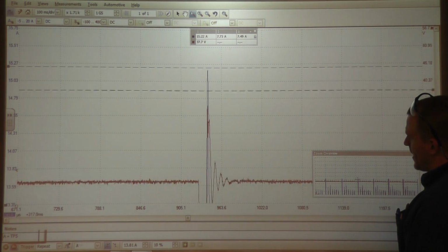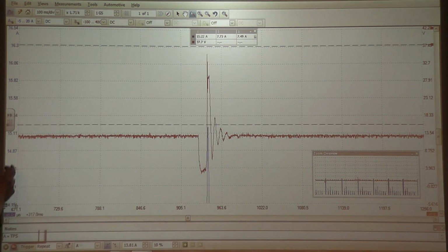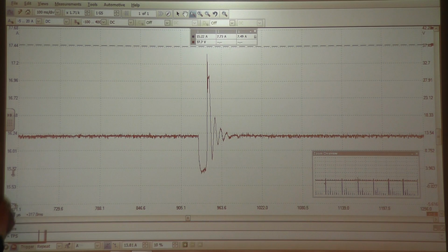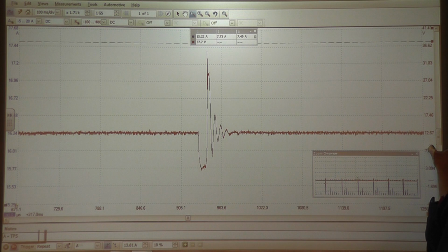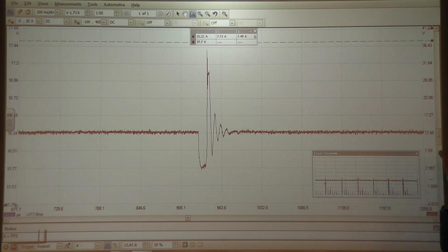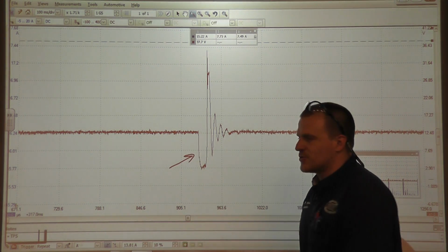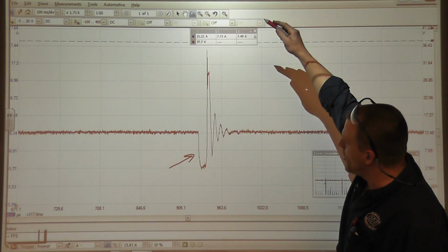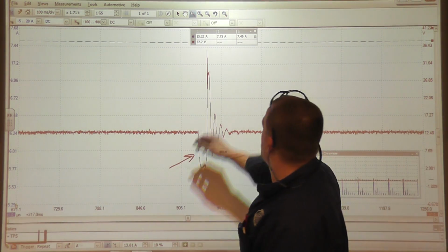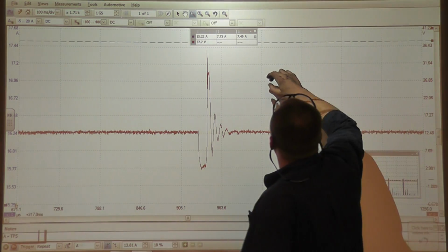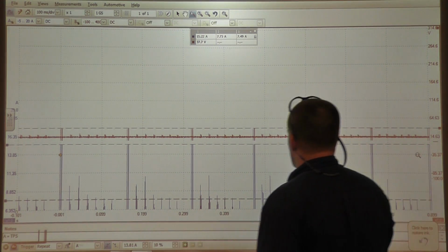We look at this red trace. That is your coil primary voltage on this same circuit. And look at this voltage waveform. It is also a really crappy looking waveform. Is the driver turning on? Yes. Is there good control on this circuit? No. There's really no spike there at all. This is a dead circuit. Really no reason to beat this to death any further. This circuit in this picture really says it all.